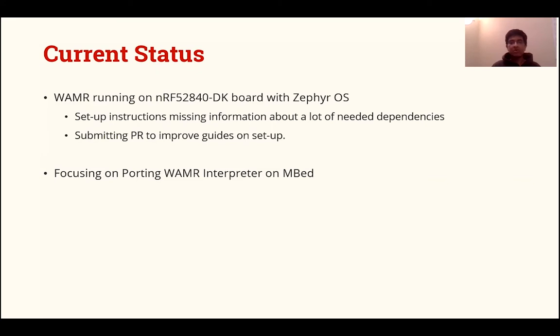We have gone through the porting guide and identified which files are needed to link which set of functions between WAMR and Mbed OS. Additionally, since Mbed is POSIX compliant and since it already has math.h library functions available, we only need to provide the Mbed platform-specific definitions. We also need to create a CMake build script for Mbed, and we need to code the API used by WAMR, which are part of the platform abstraction layer, all of which is what we are currently working on right now.